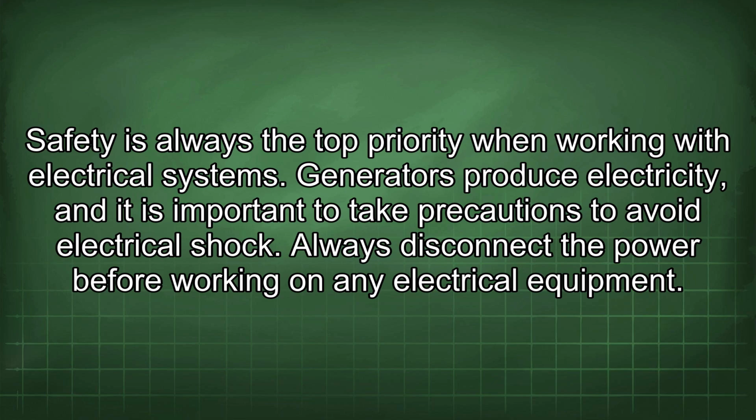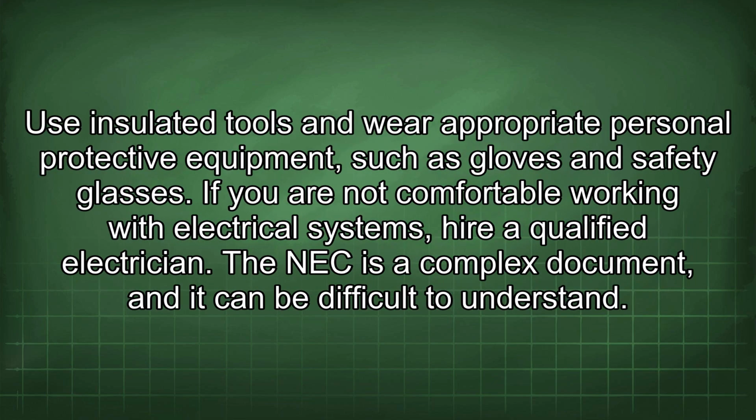Generators produce electricity, and it is important to take precautions to avoid electrical shock. Always disconnect the power before working on any electrical equipment. Use insulated tools and wear appropriate personal protective equipment, such as gloves and safety glasses. If you are not comfortable working with electrical systems, hire a qualified electrician.